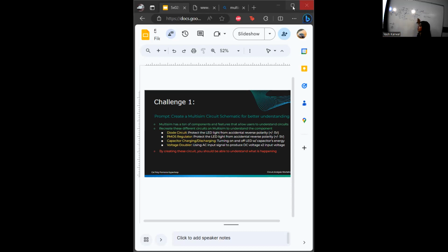And we also learned about capacitors, energy, right? So this is the concept all put together. And this circuit is called a voltage multiplier. And in ideal mode, it would be 10. But because we have to consider the 0.7 and stuff like that, it will bring down the voltages, right?